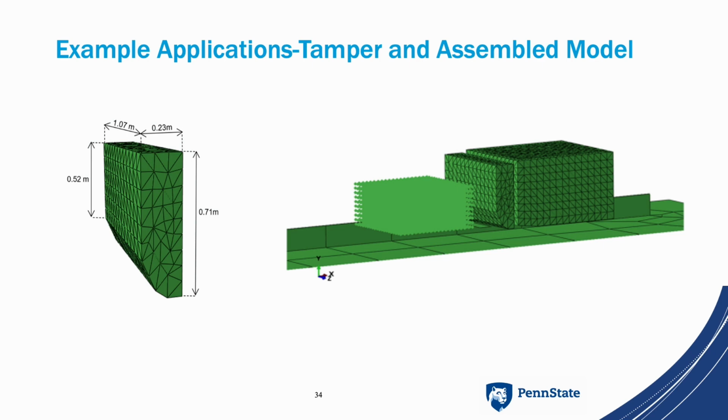The particles are released in a direction perpendicular to the inlet surface of the particle generator, and the flow rate should be determined according to the paving speed. In the study, only one particle generator was used. In order to improve the computational efficiency, the morphology of the aggregates was simplified to spheres, which cannot fully simulate the aggregate interlocking happening during compaction, because they're not going to be spheres all around.